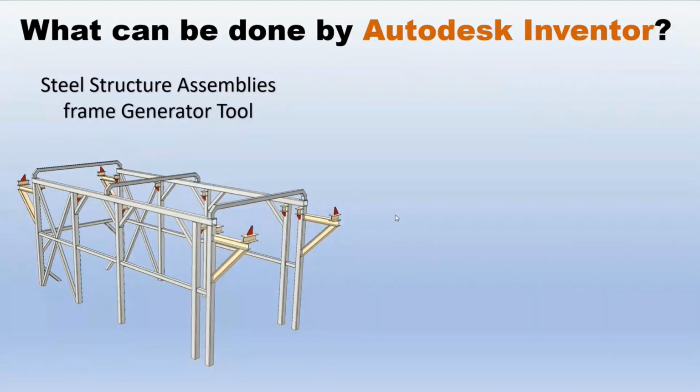After that, select the section, IPE 100 or UPN, all of that. So you build a 3D skeleton. After that, you can use the frame generator tool to convert this skeleton to a frame made from steel.